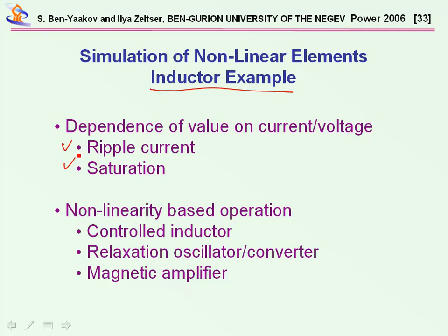Another reason for doing simulation of nonlinear inductors is that you'd like to exploit the effect of nonlinearity for actually realizing a control inductor, that is an inductor whose value you can change by a command or by a control signal.